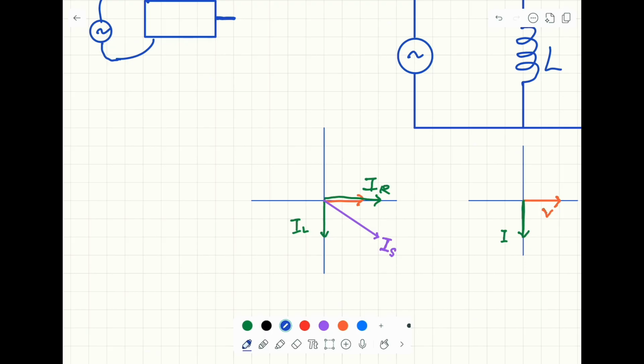Now this time we can use the current as the reference for the different types of power. The real power, which is the power converted into heat or the work done by the motor, is P here. And this is equal to V, remember, V is common for all the elements, multiplied by the current passing through the R. This time the apparent power S will be along the current.